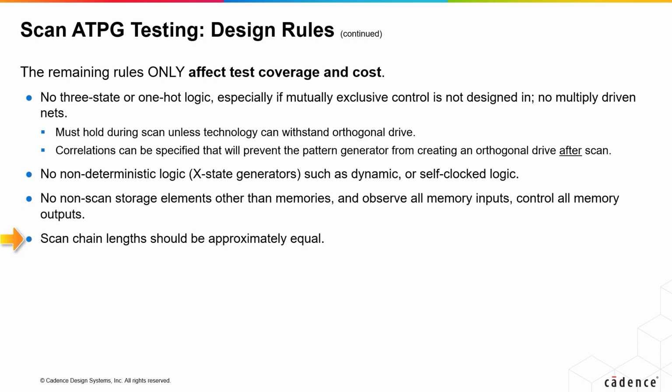The chip must be scanned for the longest chain. Unequal scan chain lengths waste space in the scan buffers for the shorter chains and take longer to perform the scan. With modern tools, scan chains should be balanced within a few percent.